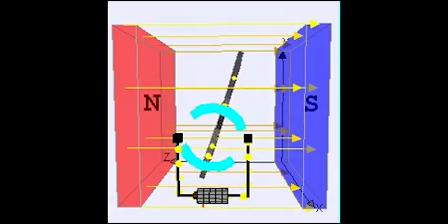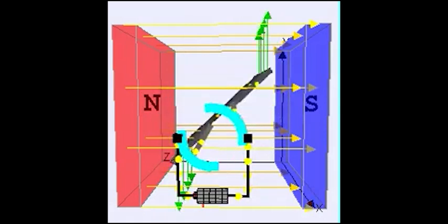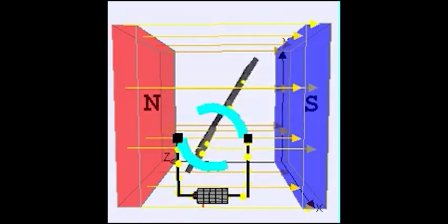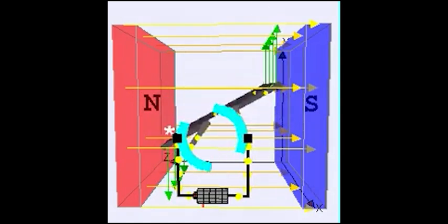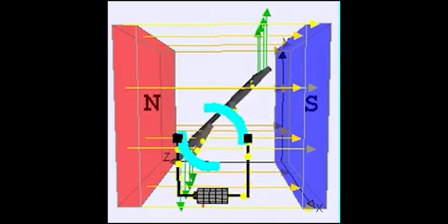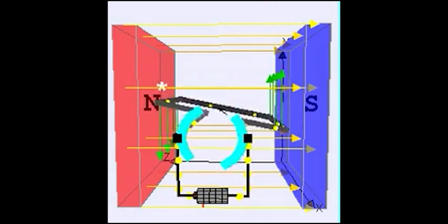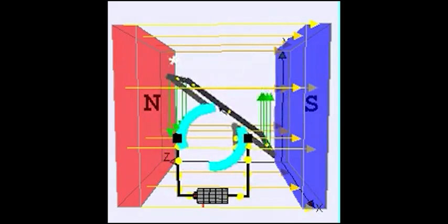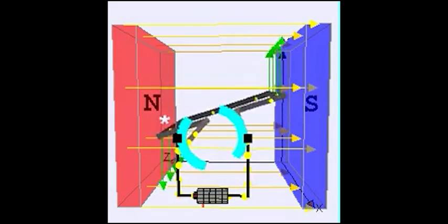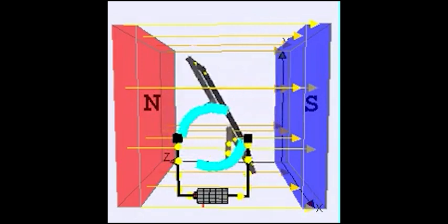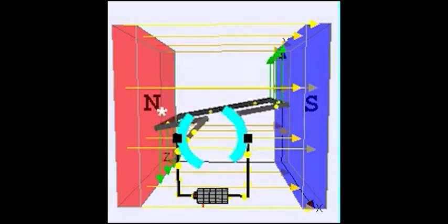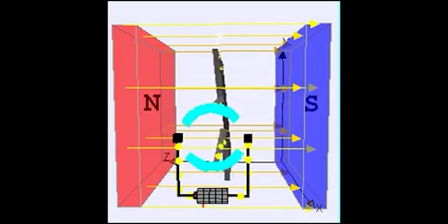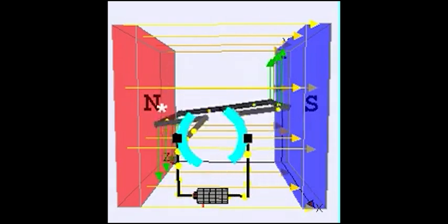The final type of rotational system is the DC machine, which differs from the first two in a few ways. The most obvious is that while the other two machines take in or output AC power, DC machines produce or are powered by DC power, hence the name. Second, DC machines are connected to the output or source via the rotor, which is composed of a loop or coil of wire. In addition to this, the stator is made up of permanent magnets.